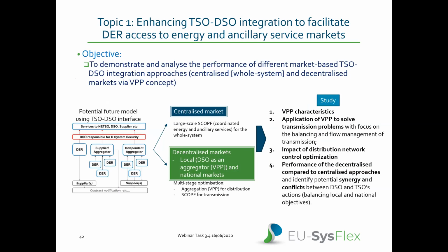So in this work, we have investigated two approaches. One is a centralized market where all energy and service providers and the users are met in a single marketplace. And the second one, the alternative solution, is to have a decentralized markets where the local markets are created to support the national markets. In this context, the DSO will be the interface between the TSO and DER using the virtual power plant concept, of which I will explain very shortly.